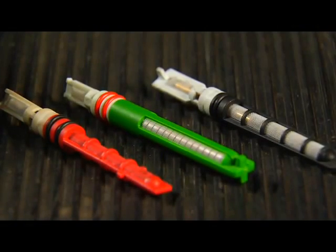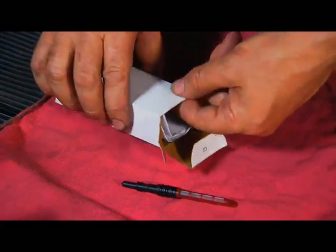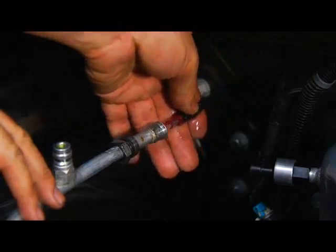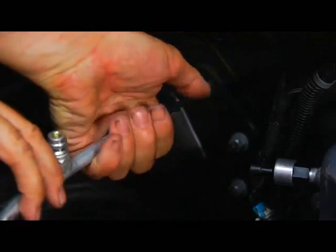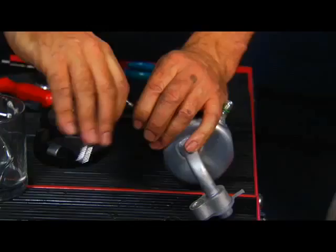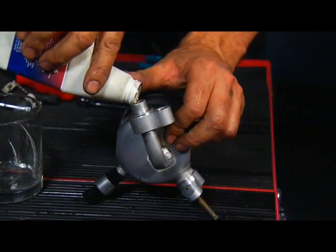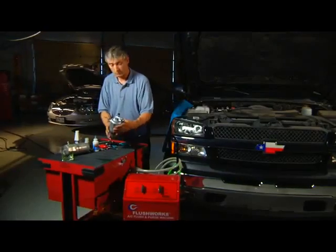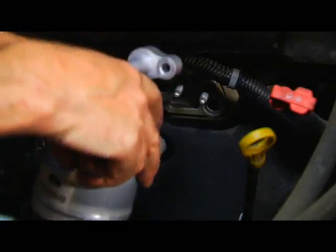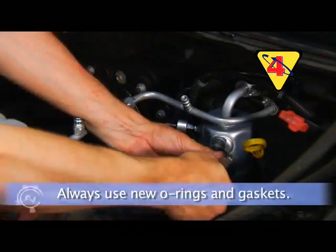It's time to install the new orifice tube. The customer asked for an adjustable orifice tube instead of the original replacement part. The automatic adjustable orifice tube will provide colder duct air during high heat load conditions. After transferring the original pressure switch and clamp assembly, pour 1/2 of the required refrigerant oil into the new accumulator. The other half was added to the replacement compressor. Remember to always use new O-rings and gaskets to ensure a leak-free repair job.